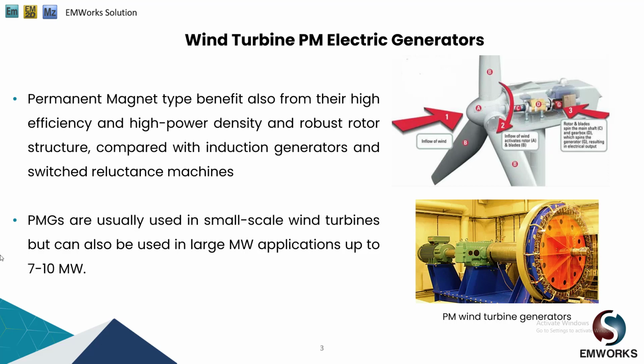A permanent magnet synchronous generator is a generator where the excitation field is provided by a permanent magnet instead of a coil. The term synchronous refers to the fact that the rotor and magnetic field rotate with the same speed, because the magnetic field is generated through a shaft mounted permanent magnet mechanism and current is induced into the stationary armature windings. Synchronous generators are the majority source of commercial electrical energy. They are commonly used to convert the mechanical power output into electrical power for the grid supply.